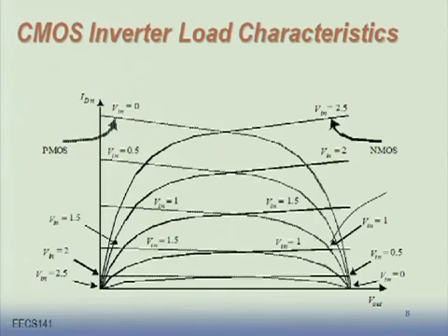So when V in is 0, what is the solution here? All NMOS curves are laying along the x-axis. The current is 0 when V in is less than VT. And it intersects with the top curve that corresponds to the PMOS transistor, where V in is equal to 0, where VGS is equal to VDD, the maximum curve. VGS absolute value, okay? So the intersection is right there.